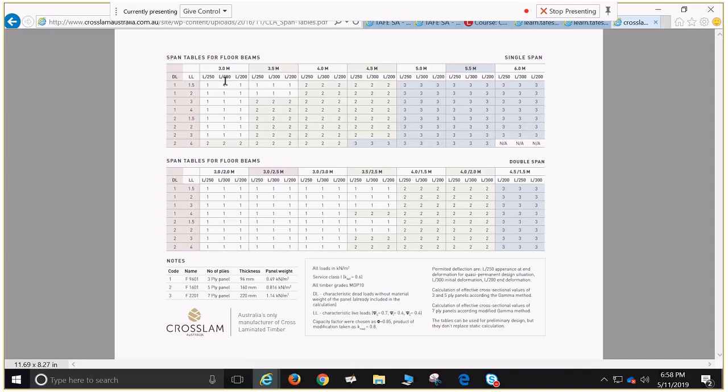Well, but not now. The thing is, that's typically how engineers design commercial buildings. Things are actually deflecting all the time. Yeah. But the human eye doesn't like to see obvious deflection. So there are tolerances around deflection that engineers will accept. They'll say we can have this many millimetres over this distance and people won't notice it. And that's the way things are designed.